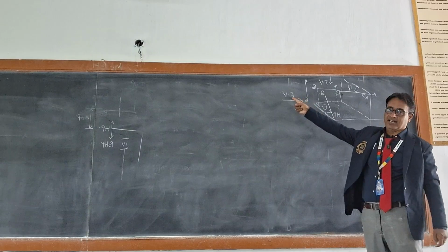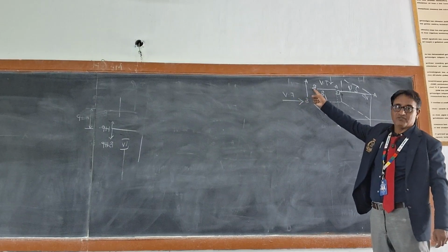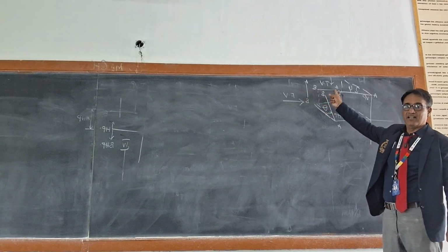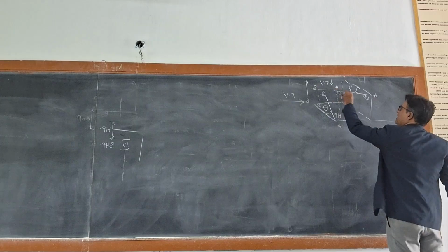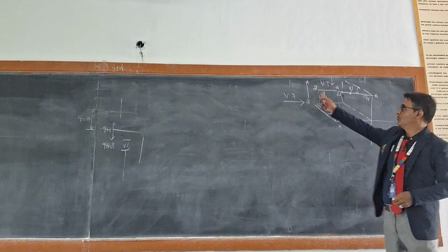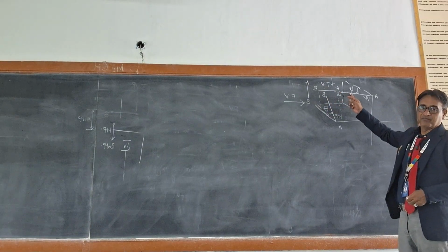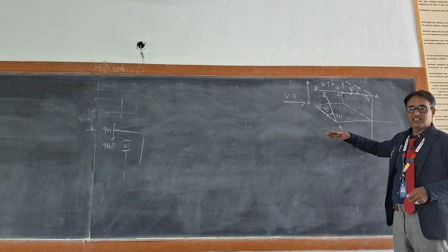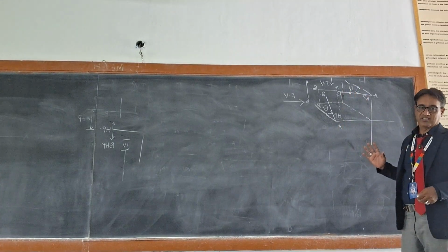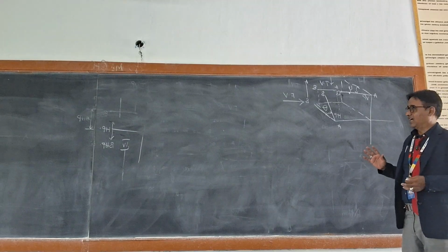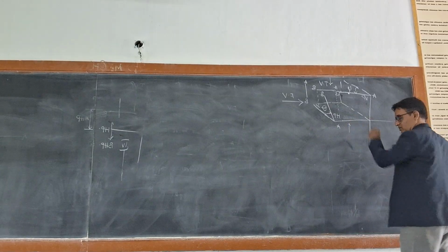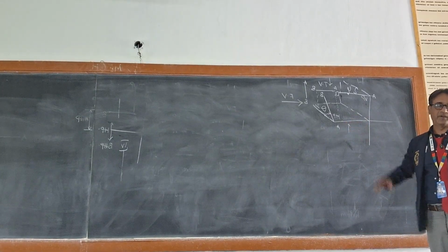When you look from the front, point B is visible and A is not visible, since B superimposes A, and that projection will be a point on the VP. It will not be a line, it will be a point. B will superimpose A, and that will be projected onto the vertical plane. So this vertical plane and horizontal plane are the delimiters, meaning the projections will impinge on these faces and will not go beyond them. At the same time, these are all transparent planes, which means you can look at the object from the bottom also.